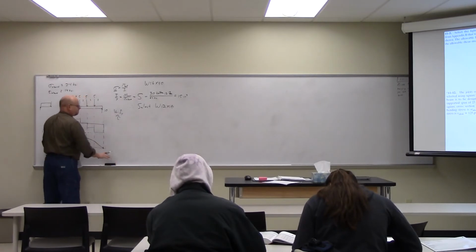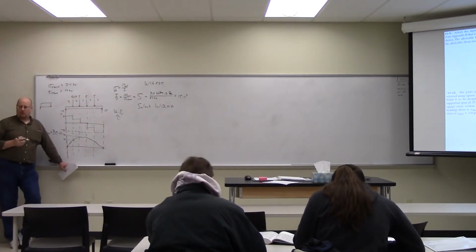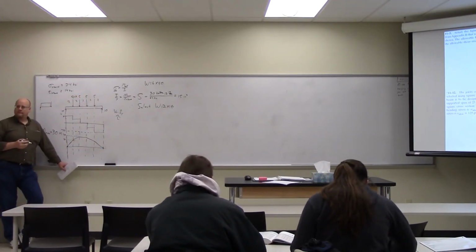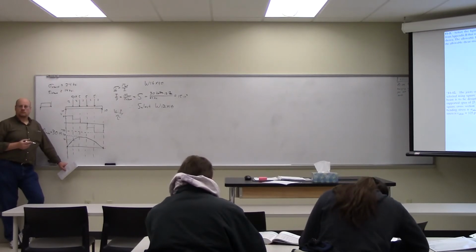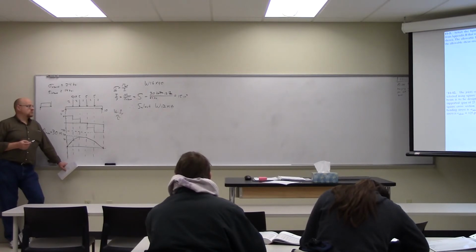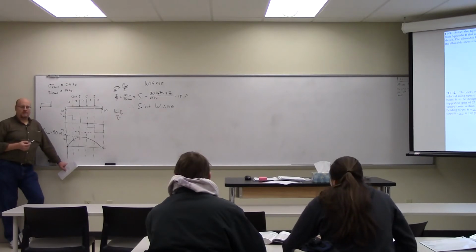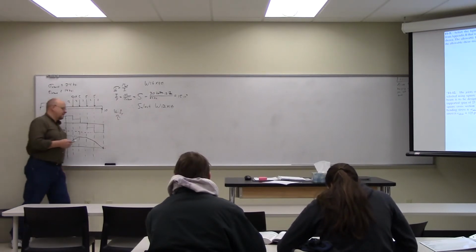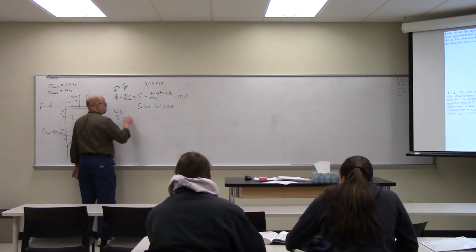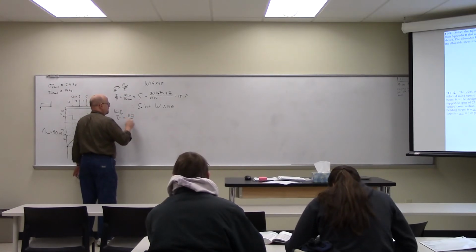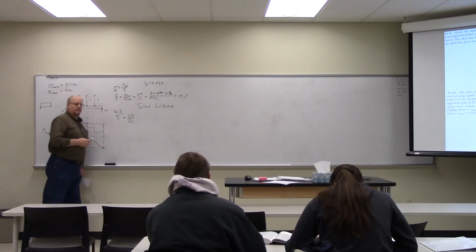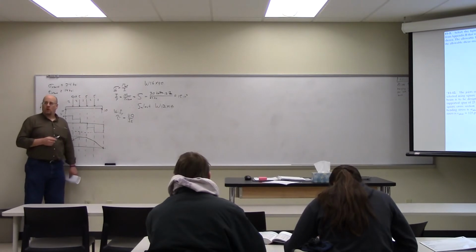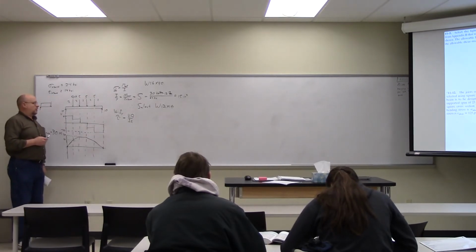Okay. How do we verify tau? How do we verify the shear stress? Plug it into VQ over IT. Right. So what value of V are we going to plug in?